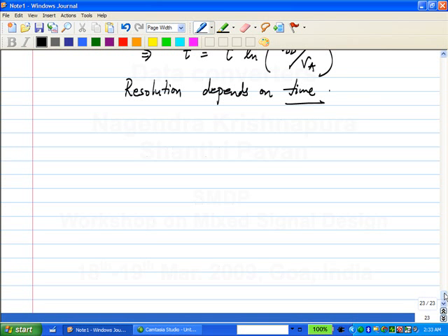So you have two inputs. Let's say they are held on two capacitors. One is charged to VA. One is charged to VB. If VA is greater than VB, now you should tell me, what should I do? Let's reuse the same idea that we used earlier. When VB was 0, what current were we pushing into the capacitor? GM times VA minus 0. Now that it's not 0, it is VB.